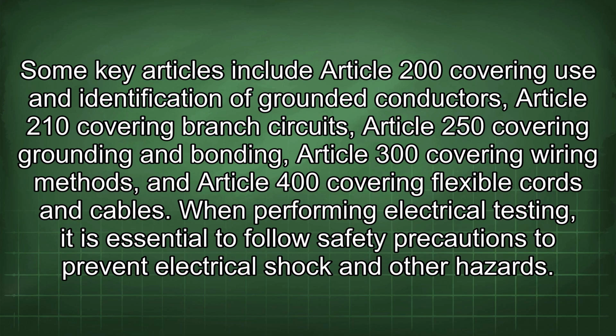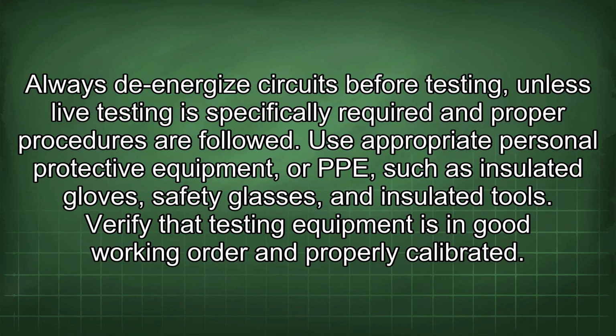When performing electrical testing, it is essential to follow safety precautions to prevent electrical shock and other hazards. Always de-energize circuits before testing, unless live testing is specifically required and proper procedures are followed. Use appropriate personal protective equipment, or PPE, such as insulated gloves, safety glasses, and insulated tools.